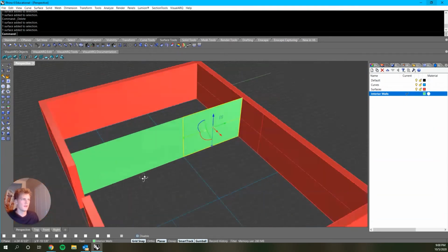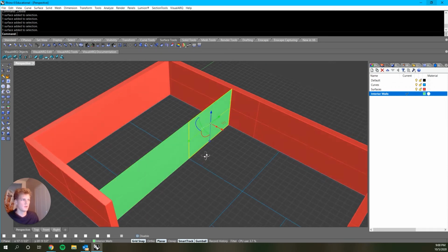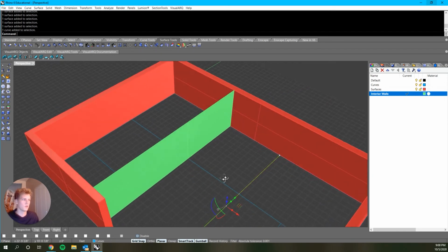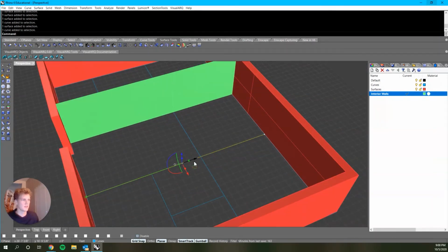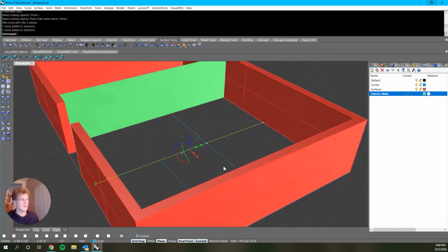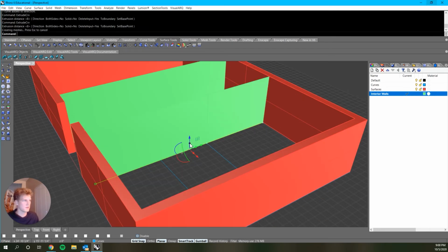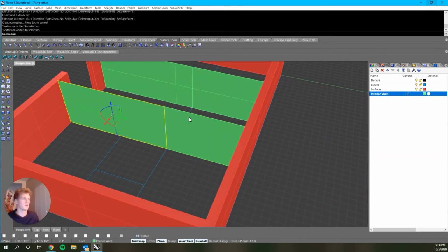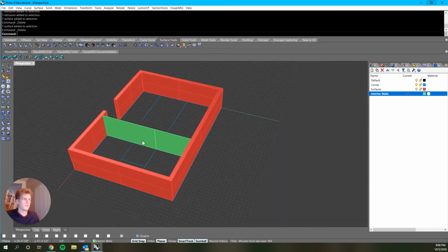After that, now you have two separate pieces, and then you could delete the cutting plane, right? So you can see there, if you wanted this wall to have a thickness different from this wall, but you were pulling it from the same curve, you could do it that way. Alternatively, you could also just take that curve, run a split, cut it with that one, and now you have two objects. And I believe if you extrude those curves up 8 feet, that should make two separate surfaces as well. So again, there's more than one way to do things.